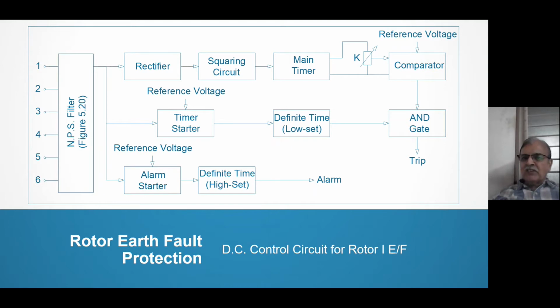And my dear friends, this NPS is class B protection. It is not class A, because the fault was not in the generator, the fault was on the transmission line. So you need not trip the generator breaker. We will trip the boiler and turbine, and then through the low forward power relay, once again, class B will return to class A.